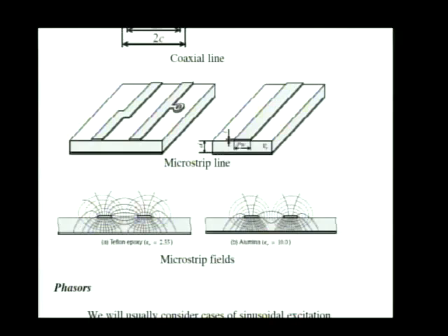Because this is the type of situation you get with integrated circuits. You have a substrate with possibly some oxides built up on top of it, and you place metallizations above and below in typical integrated circuits, and so you could imagine having one integrated circuit element, transistor, or some other type of device hooked up here, and another integrated circuit element hooked up here, and integrating this microstrip transmission line using the same fabrication technology you use for the integrated circuit.